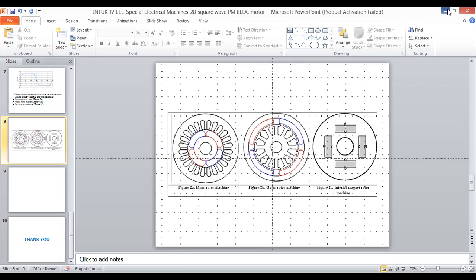Here, the stator MMF is revolving at the same speed as the rotor flux, that is the rotor speed, and in the same direction. The revolving stator MMF is the result of injecting a set of polyphase currents, phase-spread from each other by the same amount. Here, there is a phase shift between the polyphase windings. For example, if you consider a three-phase machine, this is the classification of the machine. We are observing now the inner rotor machines. Most of the motors are inner rotor machines only.